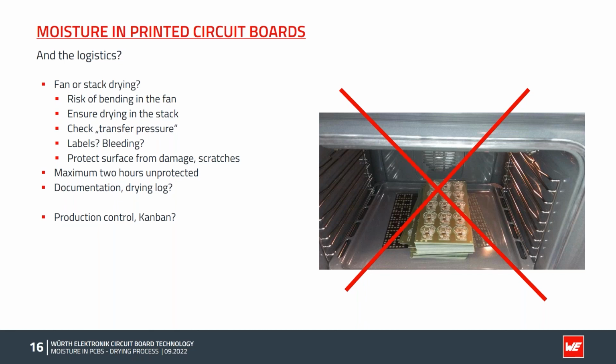On the other hand, the stack is not really professional here. It's really thick and there is no protection for a PCB and so on and so on. So please do not use kitchen ovens for that process. Normally, industrial ovens have equipment for removing the moisture, and so that's really important at that point. And do not make the pile too thick for even through drying of the stack if you're using stacks.